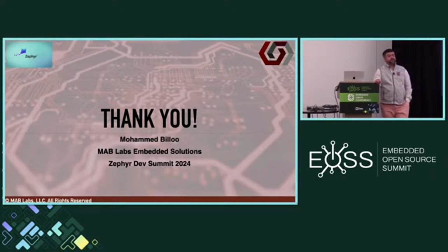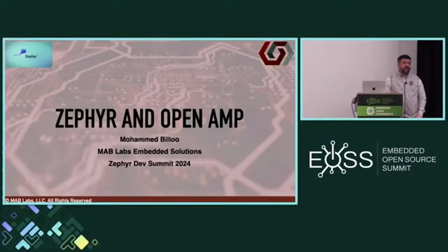I guess it would be interesting to see maybe you can have an intermediary where U-boot just sits there, waiting for the Remoteproc from the Zephyr side to say, okay, now boot, right? Because the firmware is already there, it's resident on the flash. So U-boot is just sitting there waiting, and then once Linux boots, the Zephyr side can send a message and get a message back to see if it's successfully booted or not. Yeah. So this is the next iteration in that development process.